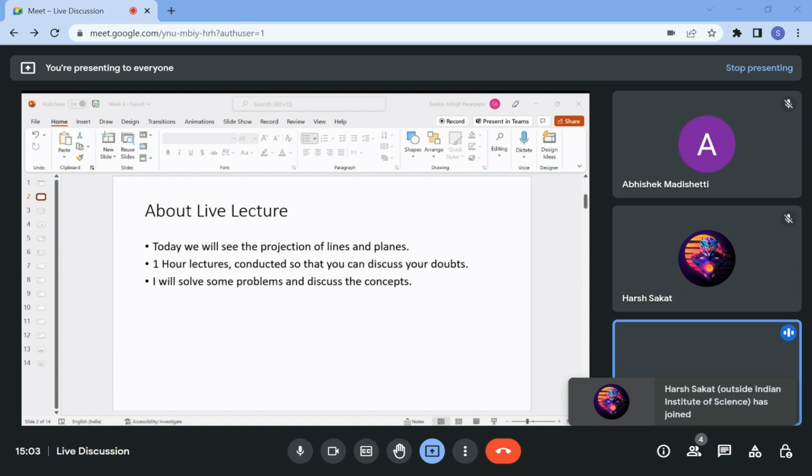Now the corresponding point in the front view is, so this was our locus where the point B should always be at a constant height because I'm not changing the angle. So this is my point B. This was our A. This was our initial B. Now let us call this point B1.